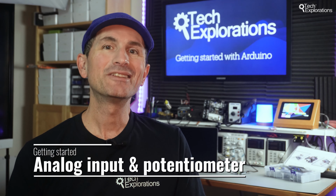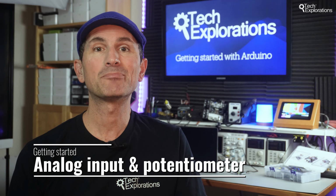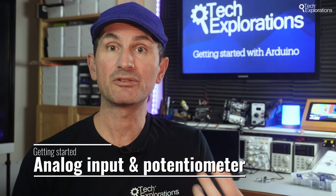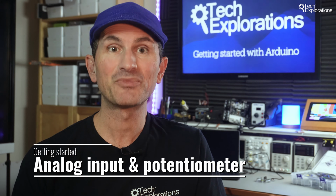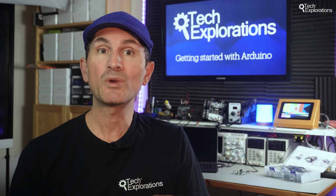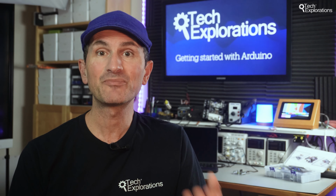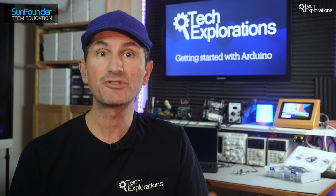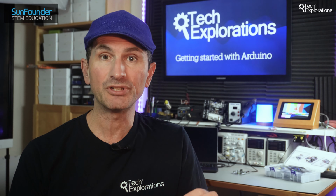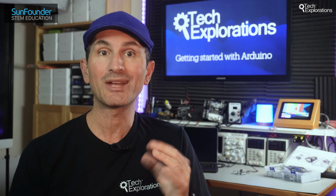Welcome back. In this video, you'll learn to control the brightness of an LED based on the position of a potentiometer. This is an opportunity to use one of the Arduino's analog input pins. Aside from the potentiometer, you can use the analog input pins of your Arduino with devices like the light, temperature and flex sensors, accelerometers, gyroscopes, Hall effect sensors, or any device that can output voltage within the acceptable 0 to 5 volts that the Arduino Uno can work with.